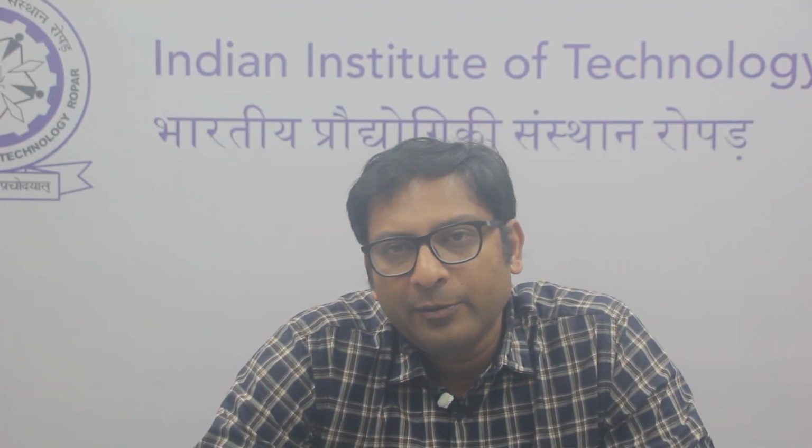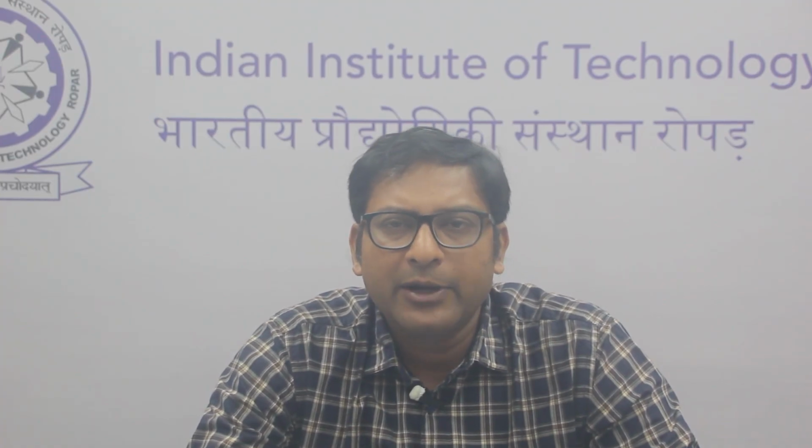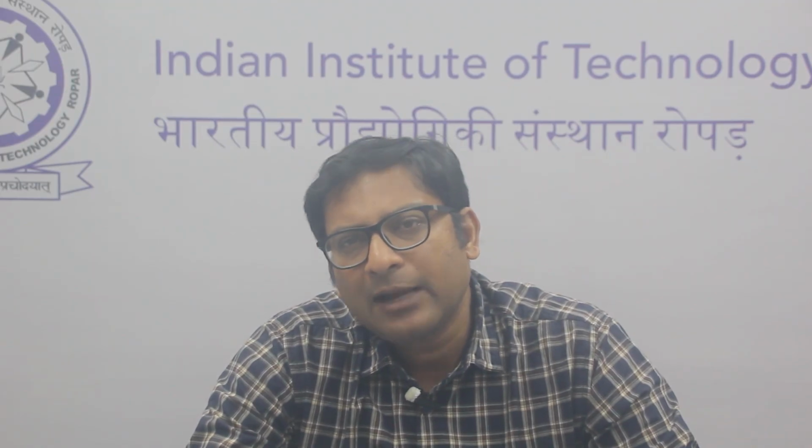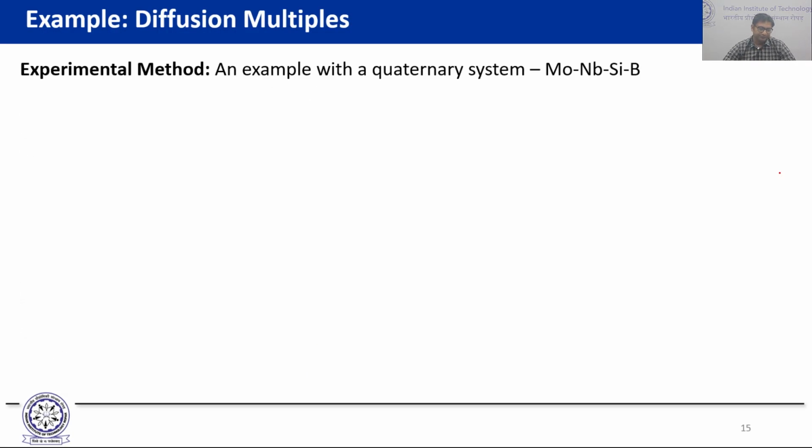Now this type of experiment can be done by annealing this diffusion multiple as a function of temperature, meaning you do the annealing at different temperature, or you pick a temperature, hold it for different time, and then when you do this entire matrix of heat treatments and you look at the EPMA profiles, from one single sample you start getting the interdiffusion coefficients of multiple sets of elements.